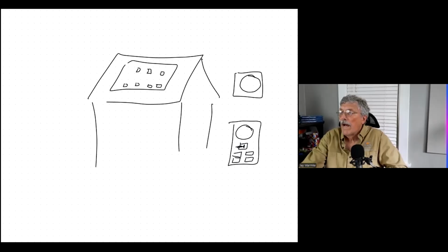So you could come out, you could go in the attic, but let's say you just come across the roof, you come down. Well, the first thing you're going to go to is Enphase has a combiner box. Then you're going to go to an AC disconnect. And then you're going to go to your meter, and you can just connect right into that double pole breaker right here in that meter. And that's your whole installation.